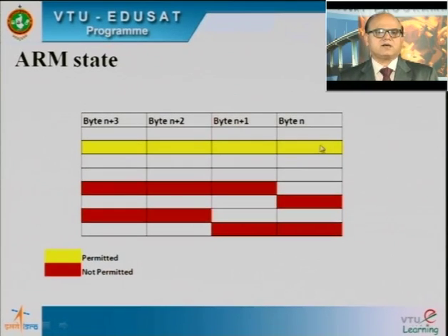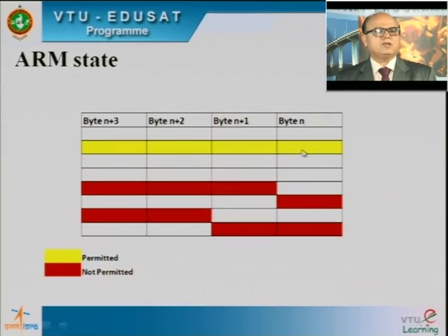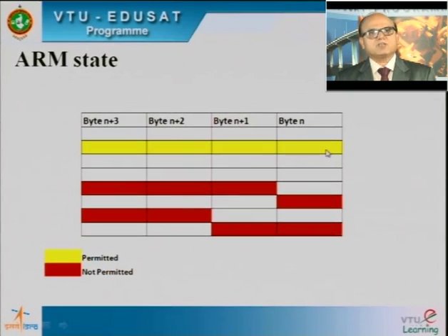As I said, in the ARM state, or the normal state of the ARM instructions, the instructions are 32 bit wide, 4 bytes long, and therefore each instruction should get loaded from a new word, or from a byte address which is divisible by 4.